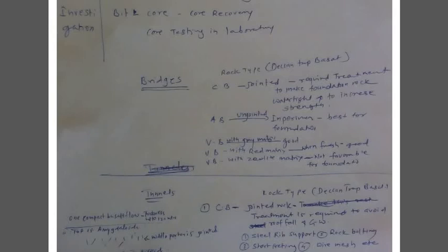So it is shown how one compact basalt flow looks. This is the compact basalt flow. This is the top of the compact basalt flow and this is the bottom. The top of the compact basalt flow is always amygdaloidal and the bottom of the compact basalt is also amygdaloidal. So the top and bottom are the amygdaloidal basalt of the flow, and the middle portion is always jointed.